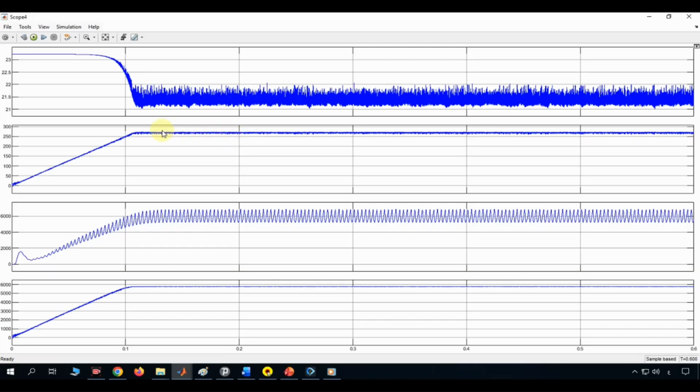The third trace is the most visually busy of the 4. It starts near 0, rises with a series of oscillations that grow larger and larger. You can see the swings getting wider as the trace climbs, and by the time it reaches the 1/10 of a second mark, it's settled into a sustained, regular oscillation, bouncing repeatedly between roughly 4,500 and 5,500, centered around 5,000.